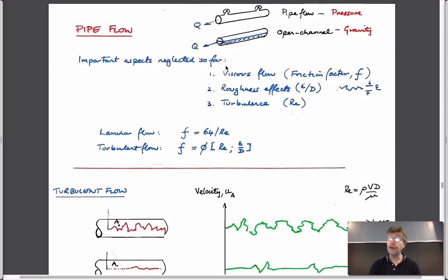We've said many things about pipe flow, but the one thing that also is useful is that we will talk in this class about open channel flows. What makes a pipe flow different from an open channel flow is that it completely fills the section of the pipe. If it completely fills the section, then applying an upstream pressure forces the fluid to go down here, as opposed to a pipe that's only half filled, where if you applied a fluid pressure at the top, it would escape in the least viscous, lowest density component, which would be the gas, and it wouldn't drive flow.